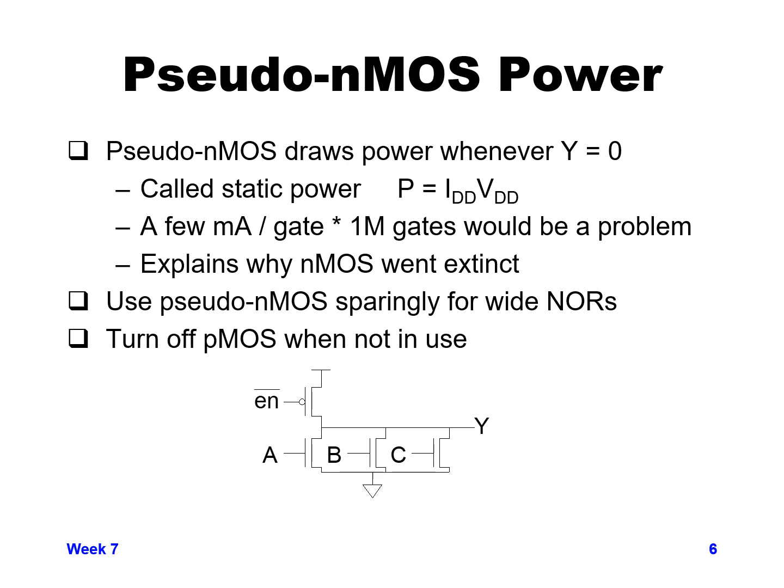Personally, I'm not sure that I would ever find it useful. I was on a microprocessor design project, I think this was almost 10 years ago now, where they were using some pseudo NMOS on 32-wide NOR gates, and they pretty much said that was the last process they were going to do it on because it was getting so power intensive.